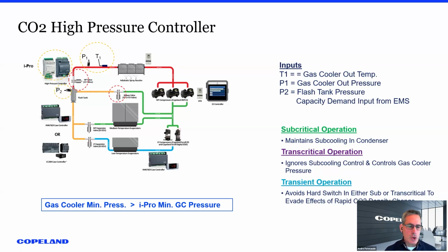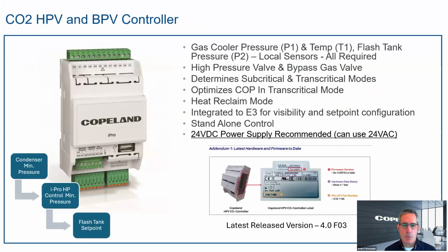But obviously what's super important here is, again, the gas cooler minimum pressure must be greater than my high pressure valve's minimum set point, so they don't fight each other. They stay in balance. Super important.